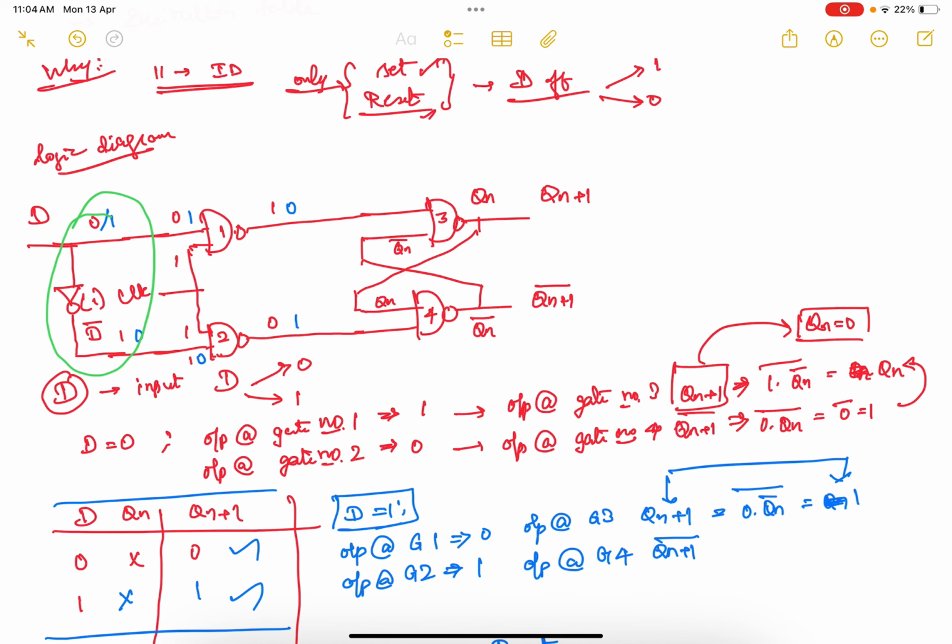Instead of adding it like this, here everything uses a NAND type of configuration, so you can also draw it like this. In some circuits they draw it this way. This is also a NOT gate, and this is also a NOT gate, so we can use any type. Whether it is a NAND-type NOT gate or a NOT-type NOT gate, everything produces a complement output based on the input. If the input is 0, it produces 1. If it is 1, it produces 0.